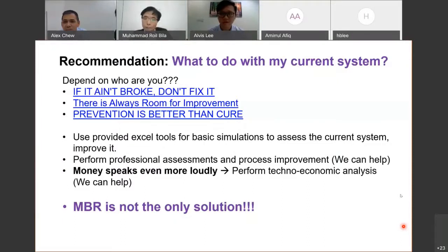Well, you can use the same membrane for up to 5-7 years. You just need to do intensive cleaning maybe once a year. So the lifetime of the membrane really depends on how you operate. If you operate with a lot of cleaning and fouling, then the lifetime will probably be less than 3 years. But if you operate it very well, there are MBRs that have been running for 20 years without replacement of the membrane.